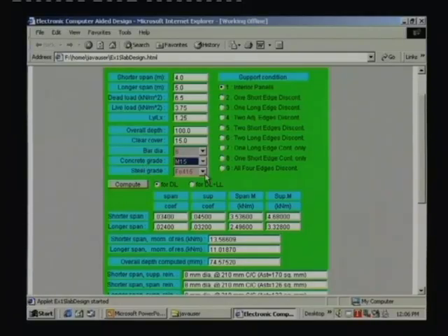And what about the steel grade? Steel grade we are having Fe 250, 415, 500, and since we mainly use 415, that is why the default one is 415. Sometimes we may check it for dead load only and also dead load and live load. That means I can either go for, this is called a radio button, so either I can check this one or I can check this one.